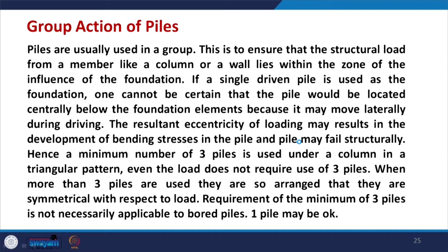Hence, a minimum number of 3 piles is used under a column in a triangular pattern, even if the load does not require the use of 3 piles. These 3 piles form something like a tripod. The load is coming from the top, and when you use 3 piles, in the plan it will look like a triangle. The locations are here, here and here. So, 3 locations are there. In a triangular pattern, these 3 piles are recommended, even if your load requirement says that 1 pile is enough, but that should not be the case for stability.